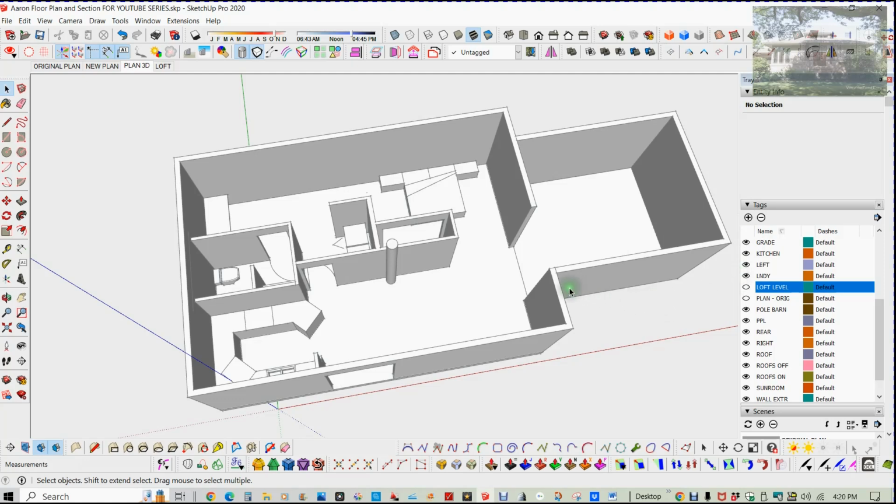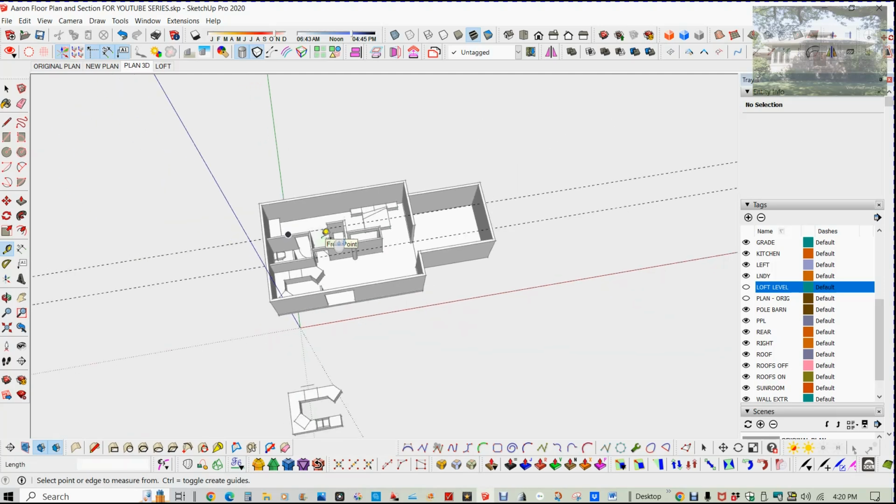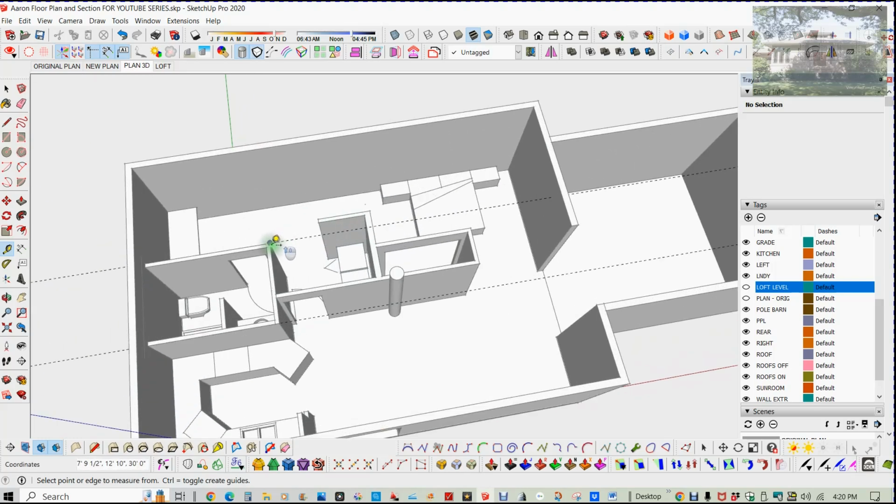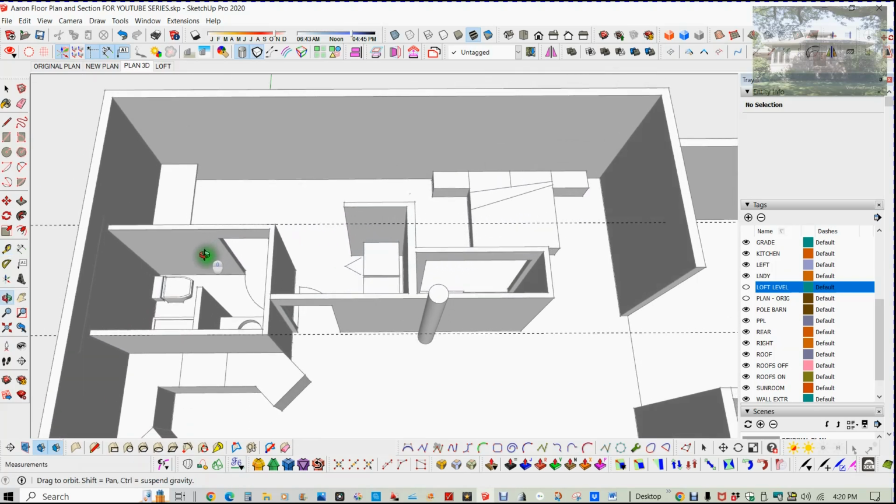The easiest way to do these things, and the way I did the first floor, I'm going to do the second floor the same, and that's use guides, which is a tape measure tool. There's a second level that falls over this restroom here and extends out across the whole room for mechanicals. So I'm going to double click with the tape measure tool and extend these walls out till they go on forever, which is nice to know that if you need to reference something from a long ways away, you can do that just with this tape measure tool and a double click on an edge.